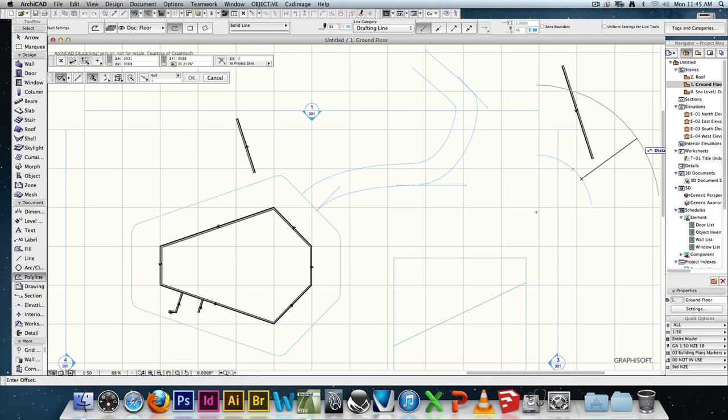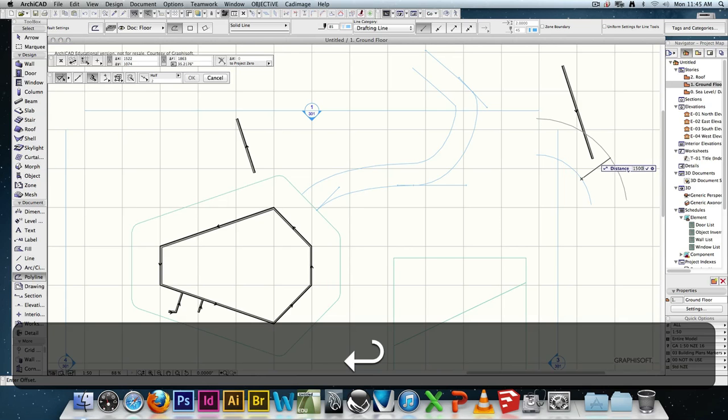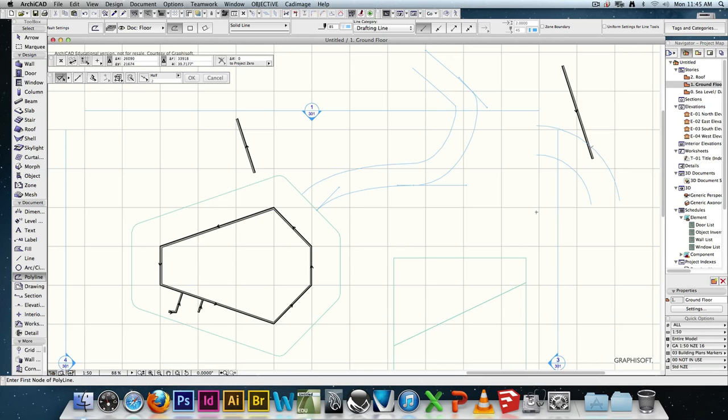See how the edge is just getting larger. I think I wanted it 1500, so I did a radius 3000. I'm going to do 1500. Cool. So that's 1500 offset from that edge. So now it's 1.5 metres. It should be 4.5 radius actually, because I think the other one was a 3 metre radius. I'm better with numbers than I am with names, by the way.